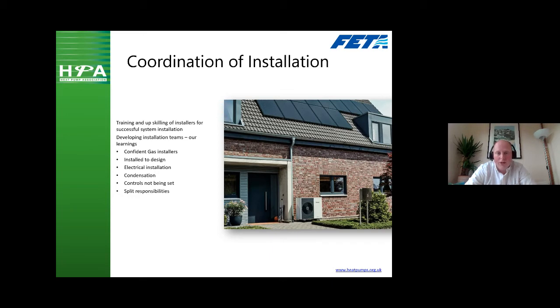water heat pump, can produce 3 to 4 times more condensation than a gas boiler, and that's because as you're taking the heat energy out of the air, you create water, and that will drop and fall out of the bottom of the unit. So you just need to make sure that that's got a suitable space to run away from, and it's making sure that